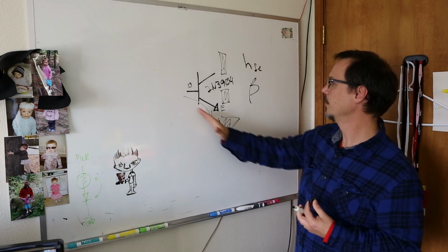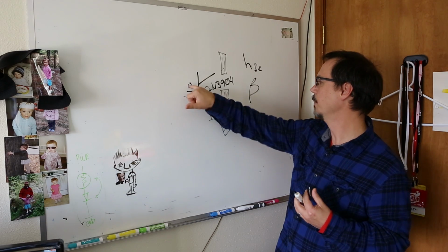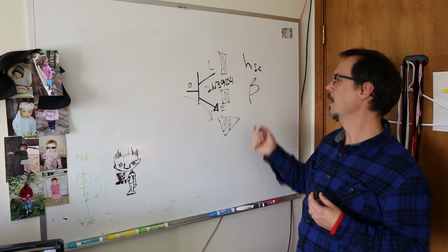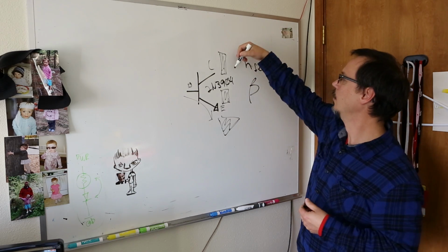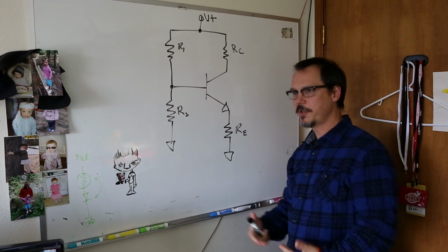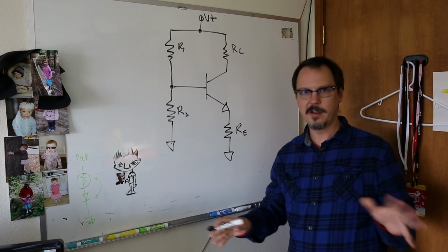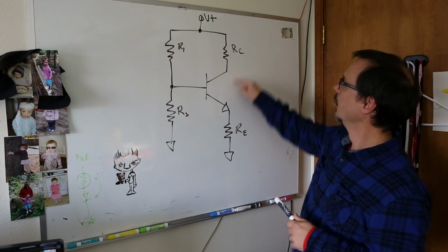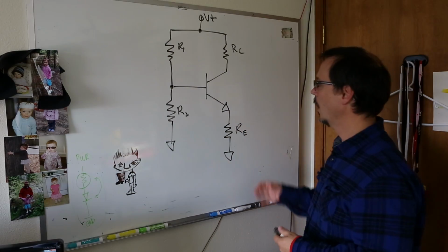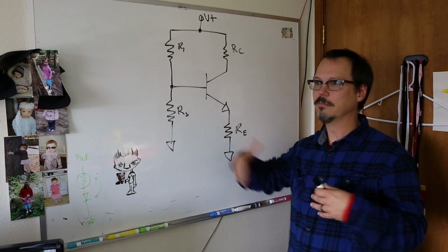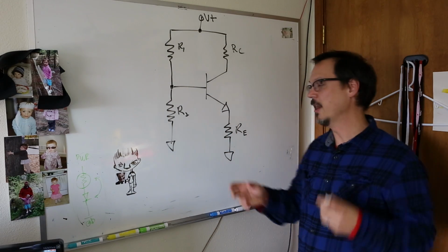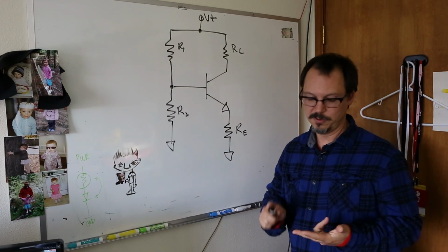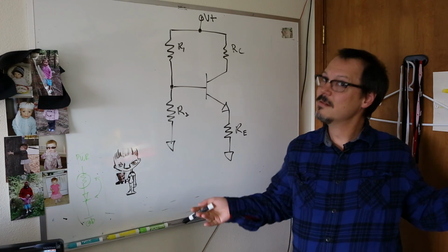The idea is, 1 microamp through the base-emitter junction will give you, at a factor of 100, 100 microamps going from collector to emitter. The first thing you gotta do before anything else can happen, you got to turn the transistor on. You get a small current going through here, gives you a large current going through here, right? Which means setting it up with a DC quiescent state, right? Because the reason we want to use this thing is to pass an AC signal. Could be audio, could be RF, could be a sensor, could be a lot of different things.